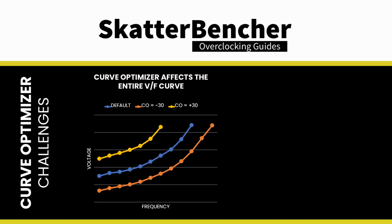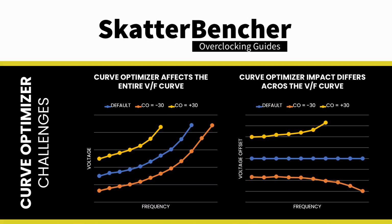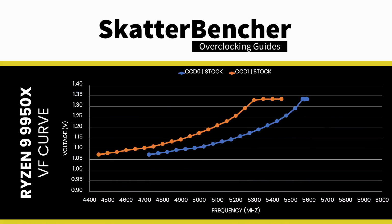Curve Optimizer impacts the entire voltage frequency curve, so it affects stability across the entire range of operating frequencies, from 600 to 6000 MHz. The same Curve Optimizer value also impacts differently across the curve. Of course, having a CPU with two CCDs, which each have their own VF curve, makes the tuning process a lot less straightforward than CPUs that just have a single CCD.